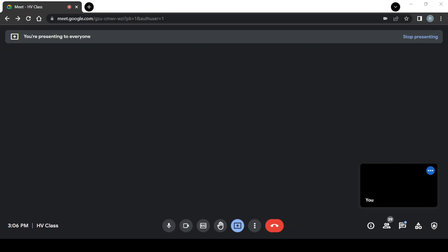The last one is a sphere gap here. As I mentioned, it can be used to measure DC, AC, and impulse. There is a limitation in the gap distance, of course, because we are using the sphere gap. We cannot increase or decrease it. They have a certain range that can be used, because when we are talking about sphere gap, we are dealing with the breakdown voltage of the air.